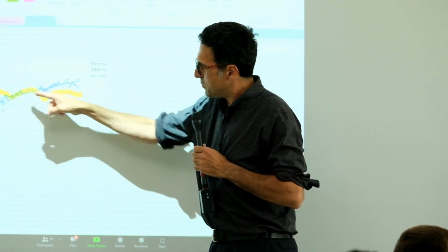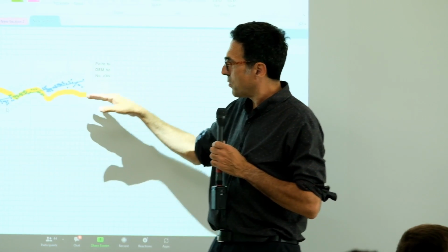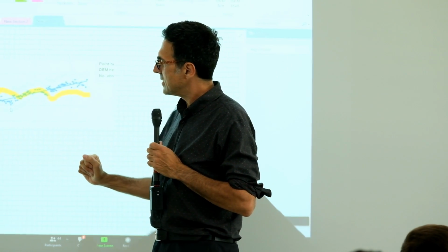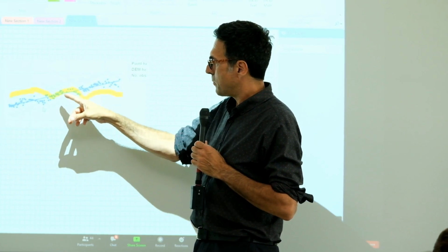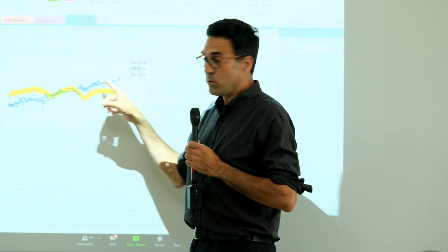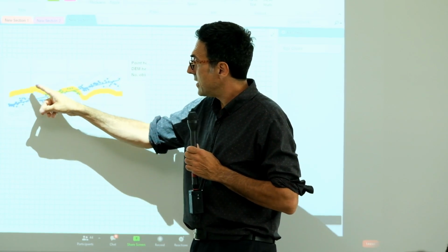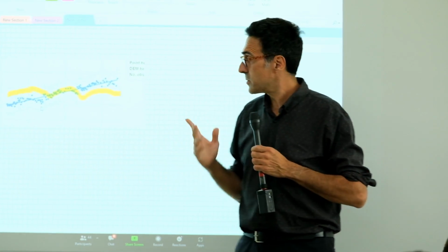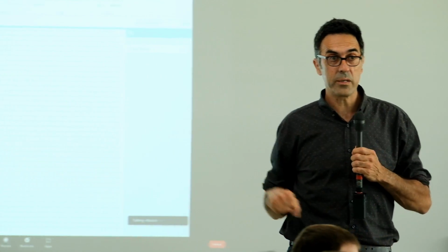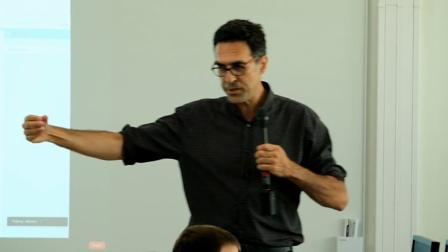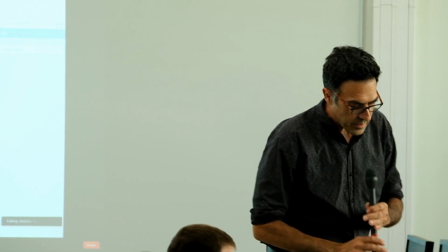So we have basically these dots, and we can find our route through this whole time series. Most likely here, at this particular point of the bridge, the blue line is the wrong interpretation. Most likely it is this kind of pattern, and this matches with what we would expect for thermal expansion in summer and winter, right? So basically this is a long bridge, steel construction. So in summer it's warmer, the bridge goes out, so this point goes to the left and this point goes to the right. And we can check that.